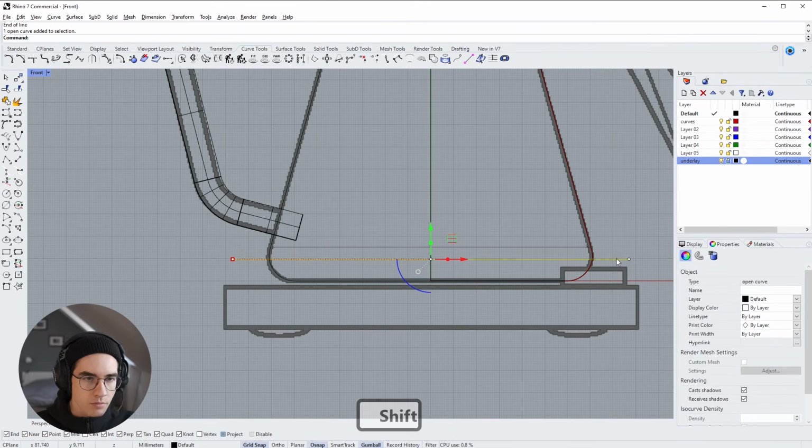So hit once. The next step for me is to create the cut. But since in reality, those material cuts are always a little bit bigger than you think, so it will never be at 0, we want to create a little bit of a distance.